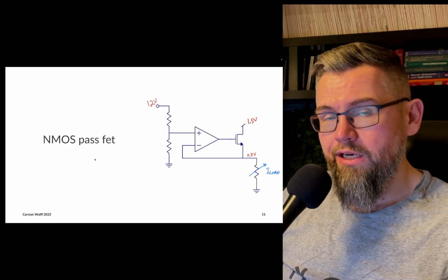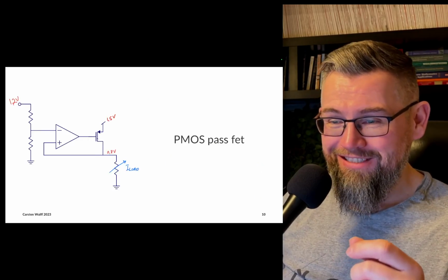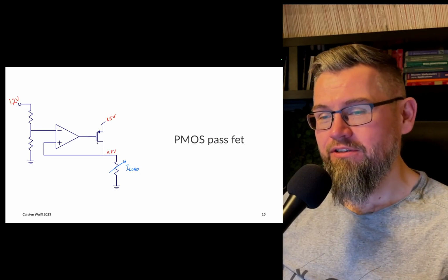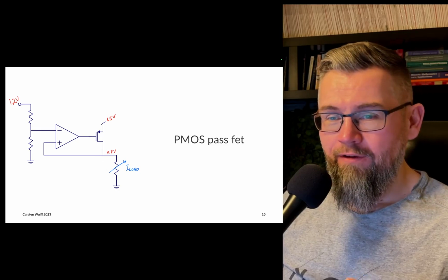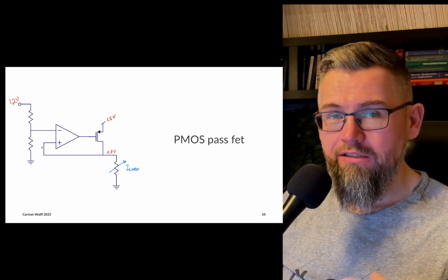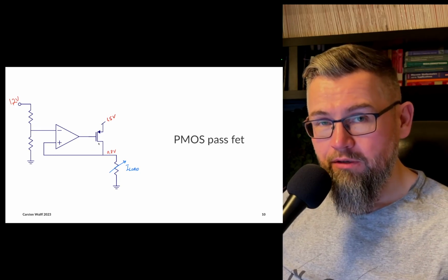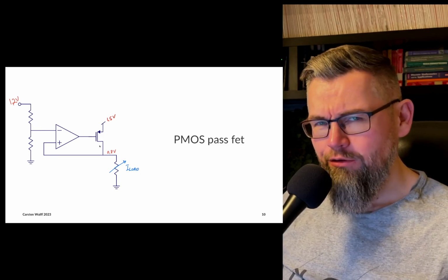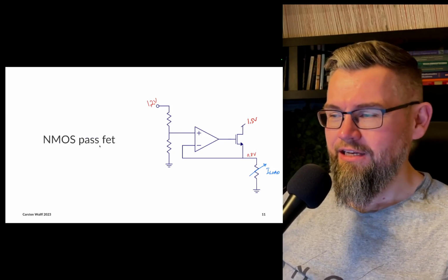Now, of course, when I say a size perspective, it depends whether the PMOS in your linear regulator actually matters. I mean, if the op-amp or the decoupling capacitor, or the reference ladder or the band gap is a lot larger than the PMOS, then you don't care. If the PMOS is half the size of the chip, which happens, then you care. And then using an NMOS is better.